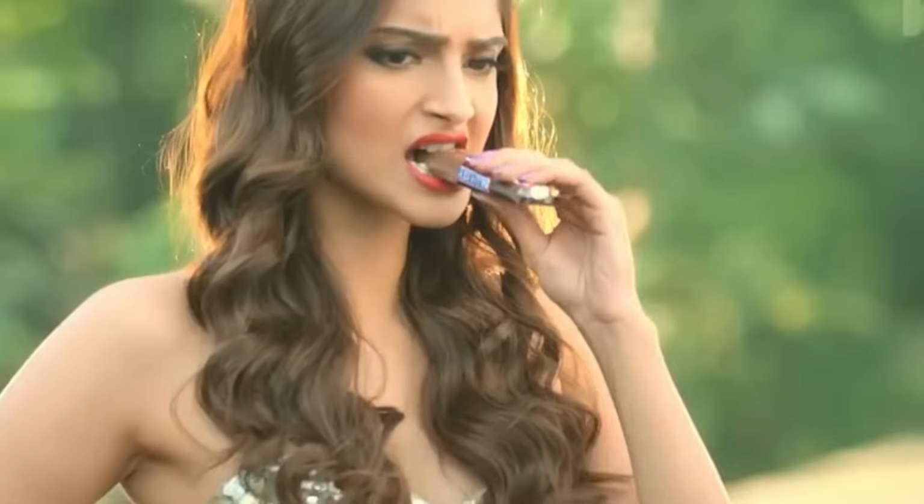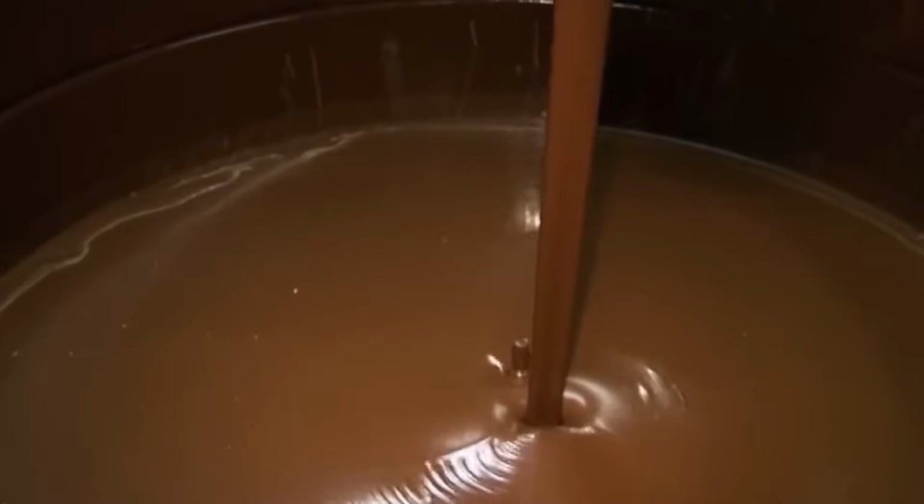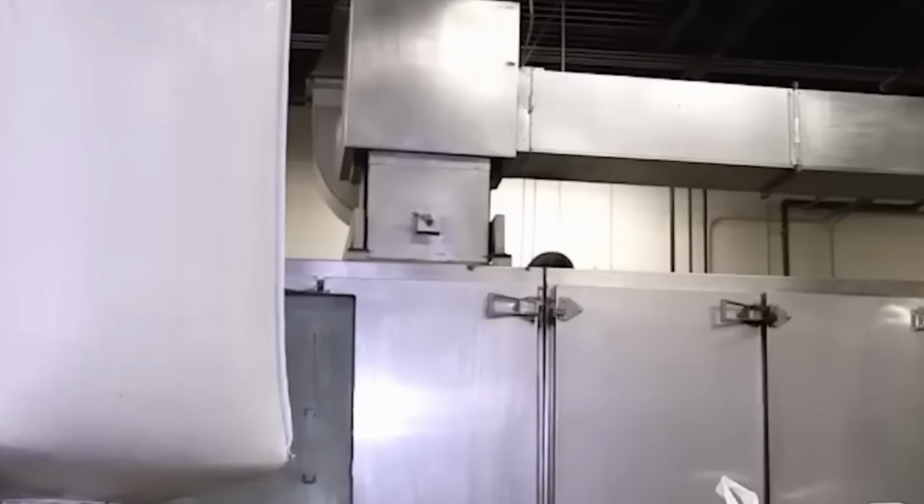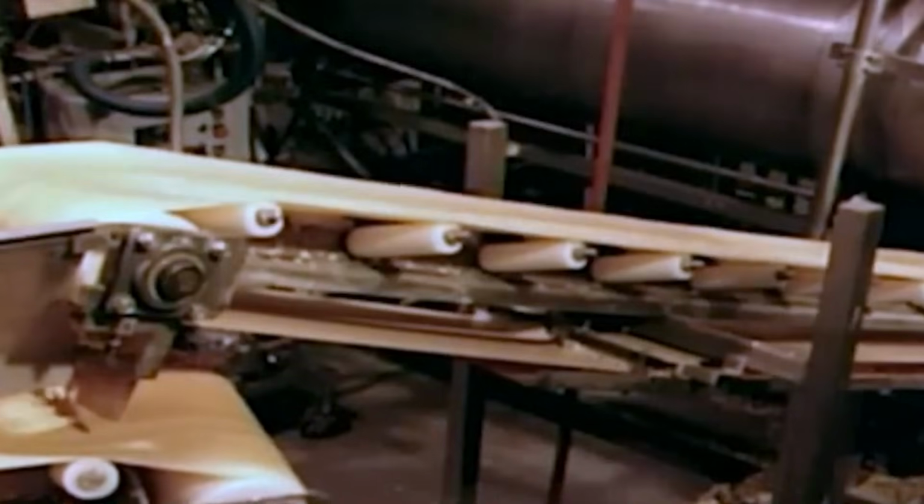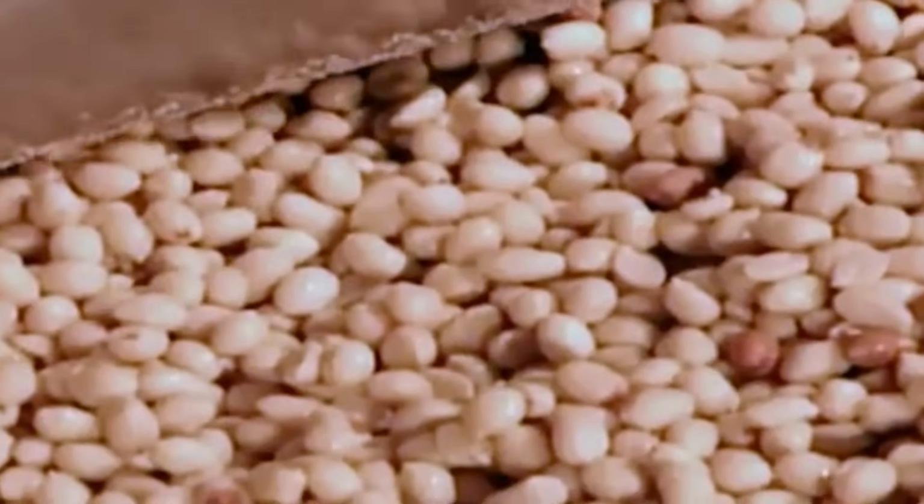Dry powders are handled in gravity-fed bins, while oils and syrups are stored in jacketed tanks with agitation and temperature control to maintain fluidity. Peanuts used in the formulation are first screened for foreign matter using rotary sieves and magnetic separators, then conveyed into buffer hoppers feeding a roller mill that cracks them into uniform granules.